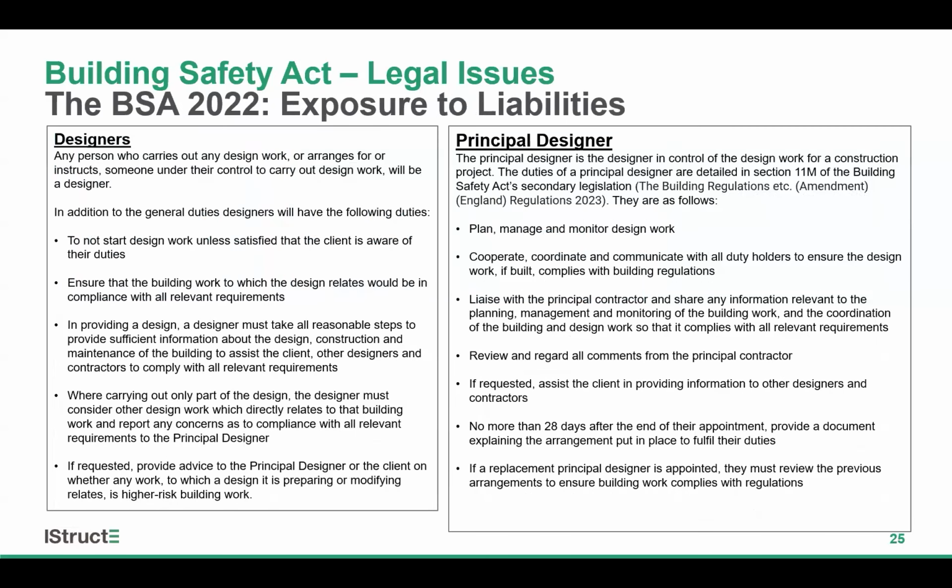So this slide intends to draw out the distinction between the roles of the designer and the principal designer under the Building Safety Act. So broadly, the designer is any person who carries out any design work or arranges for or instructs someone else under their control to carry out the design work. And so that will almost certainly be the role of the structural engineer at the minimum. And you'll be responsible for design work, coordination, and ensuring that it complies with the building regs and the relevant requirements.